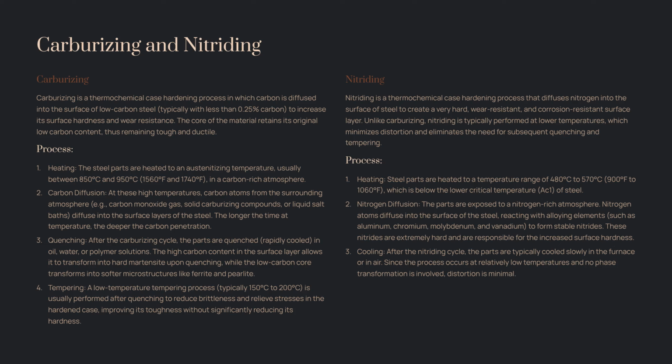High surface hardness produces a very hard and wear-resistant surface. Improved fatigue strength. The combined effect of carbon and nitrogen diffusion enhances the fatigue resistance of the treated parts. Good ductility of core maintains a tough and ductile core. Disadvantages and safety concerns. Toxicity.